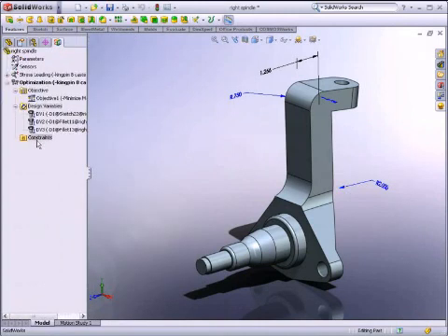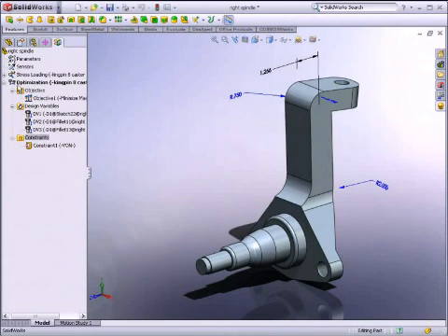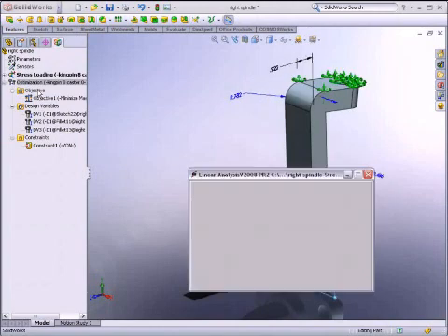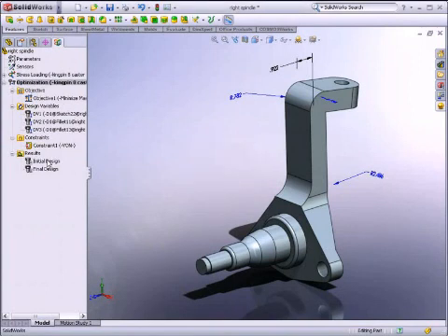Next, you must apply the constraints. A constraint defines the limiting factor for the design, which is the criterion that it must satisfy in order to be successful. With all the parameters specified, you can now run the optimization analysis. After the analysis is completed, you can then visualize the optimization by switching between the initial design and the final design.